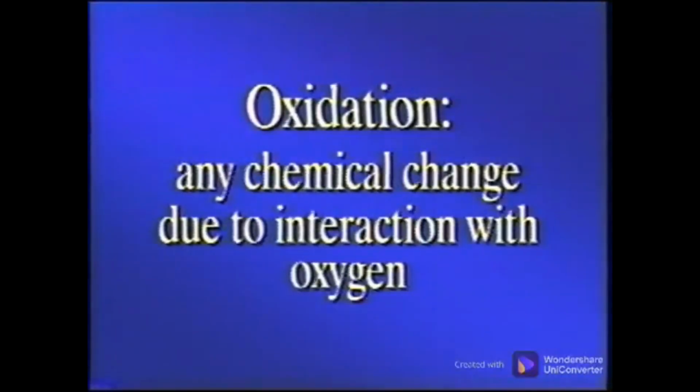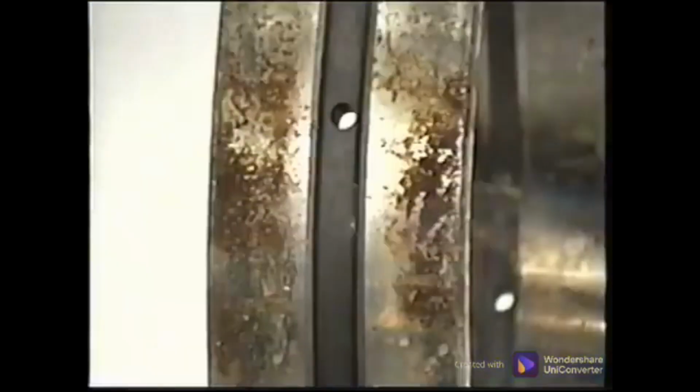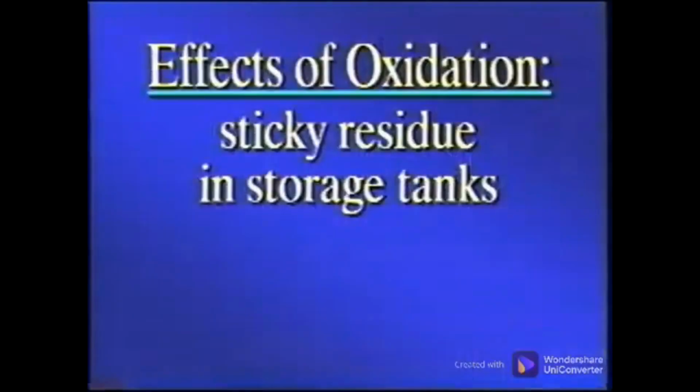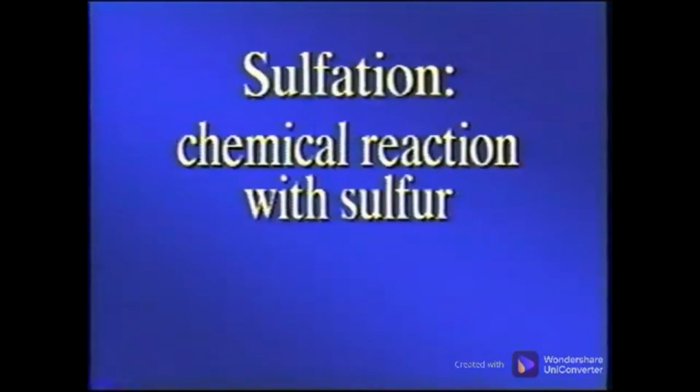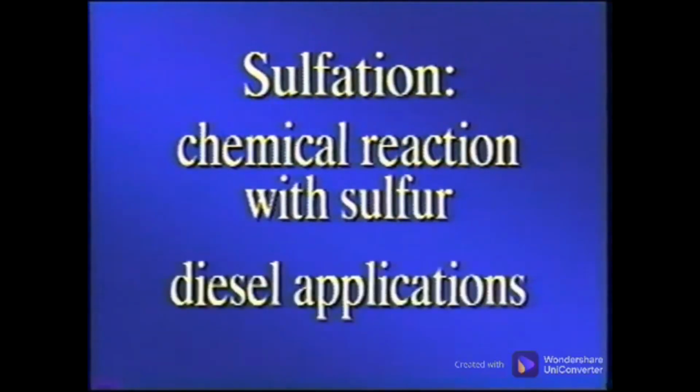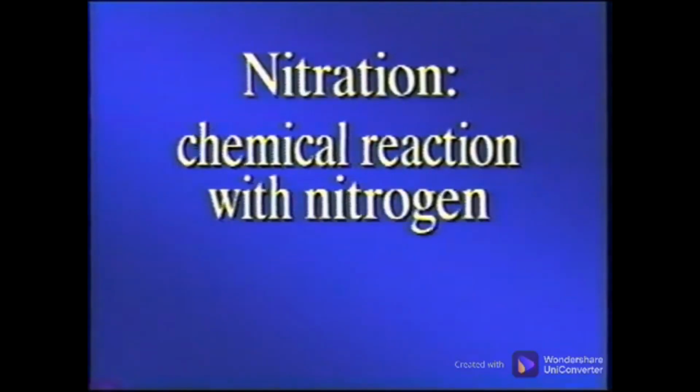Oxidation is any chemical change due to interaction with oxygen, usually in the presence of heat. Iron oxide, for example, is rust. The effects of oxidation are seen as the sticky residue lining the sides of oil storage tanks. This gummy residue is called varnish. Sulfation is a chemical reaction with sulfur and is usually found only in diesel engine applications. Soot as a byproduct from the combustion process is also usually present. Nitration is the chemical reaction with nitrogen.